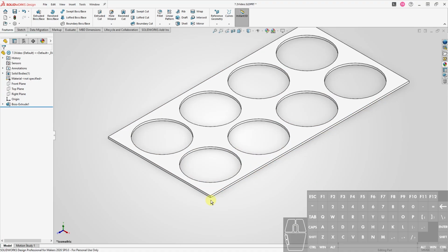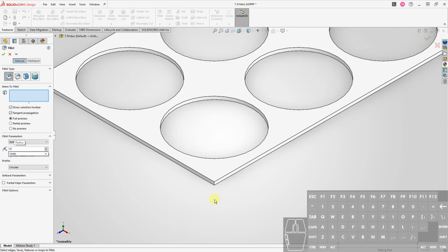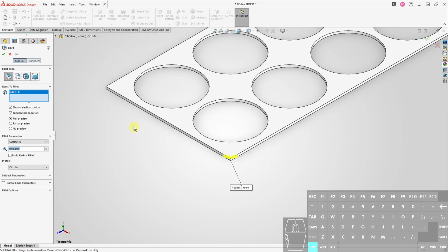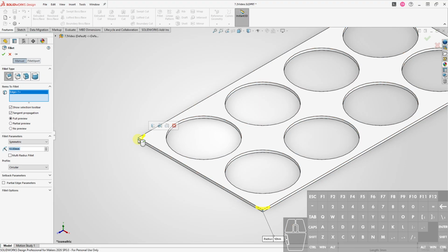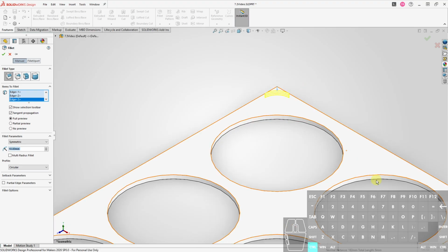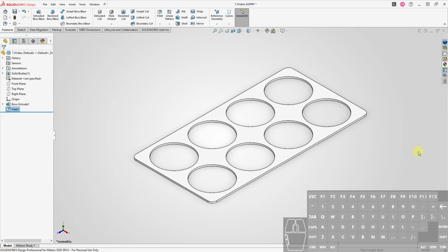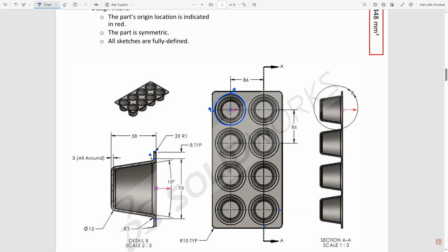Let's go ahead and fillet these edges right here. So we'll hit S, fillet, and it looks like that's going to be 10 for each of these. Let me zoom in so I can actually select these edges well. This one, and this one with X-ray vision, and then this guy right here. Okay, so we got those corners filleted, and we might as well try filleting these loops on the top and the bottom as well, because those loops have fillets with radius 1, so on the top and the bottom loop.